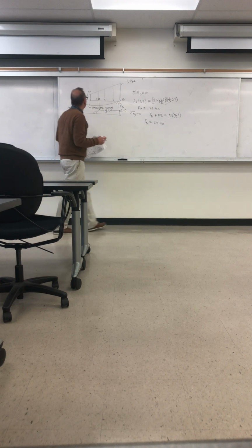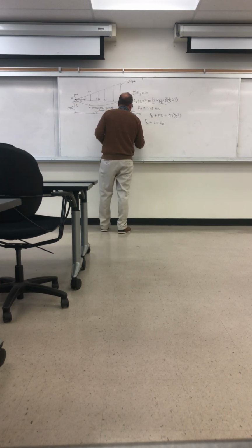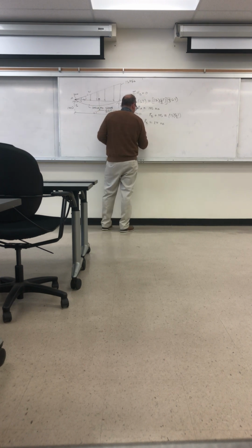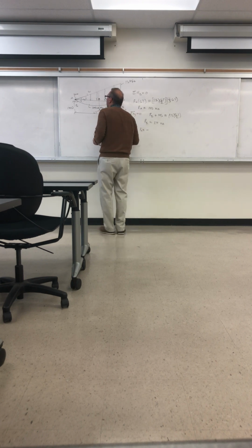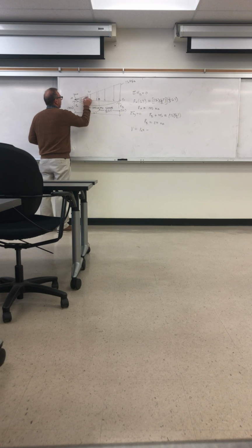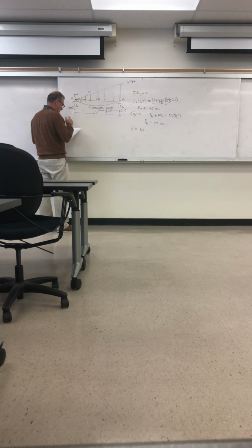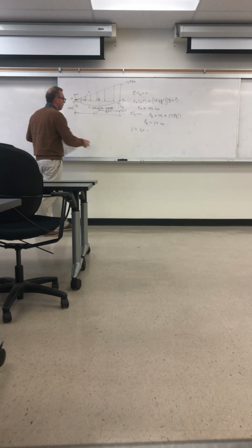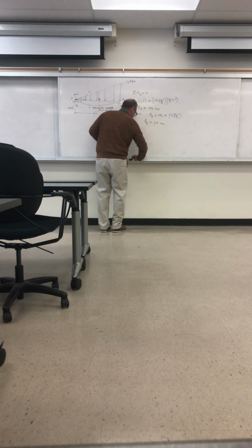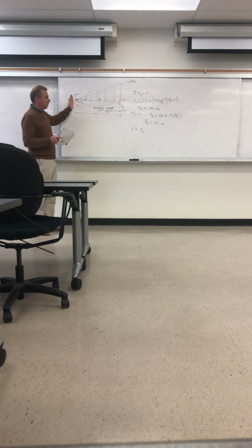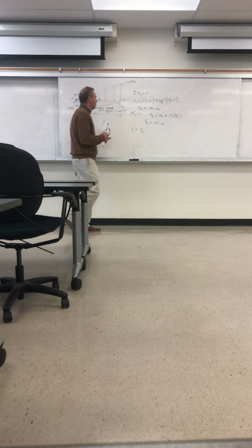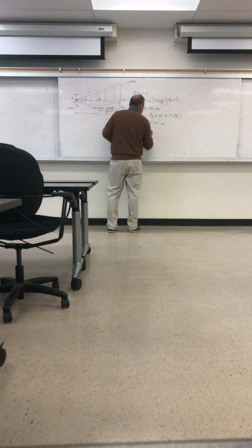So I'll write it over here, the shear expression is the reaction A. The shear is, at the beginning, just the vertical reaction as we go into the beam, and then it's minus whatever's happened up to that point, so it's minus W x over 2.